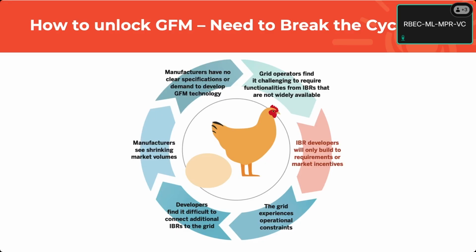Because it's probably just going to help you work better. Another case in point: about 3 weeks ago, we had an event in a region that is currently forbidding grid forming. We've done a bunch of studies, some for ESIG, and a ton in Hawaii and Australia and other places, using real code models, showing that it's working well. They're not unstable. They're very stable. What happened in this one region is that there was a large plant, let's say 200 megawatts. And it starts to oscillate in the real system. The operator shut them off because they're unstable.